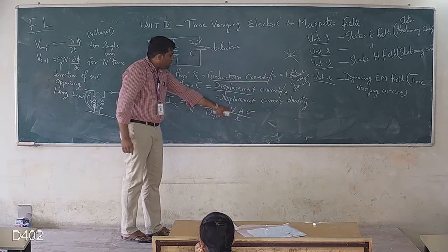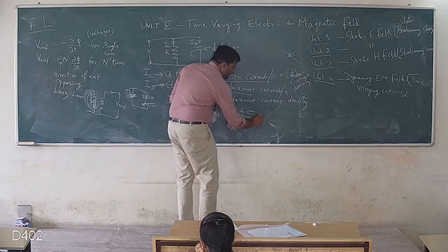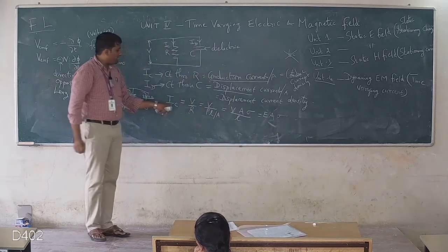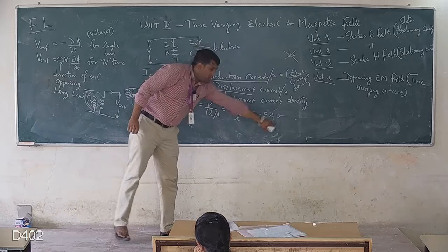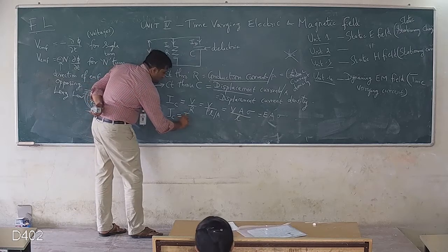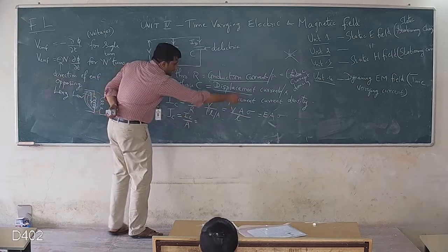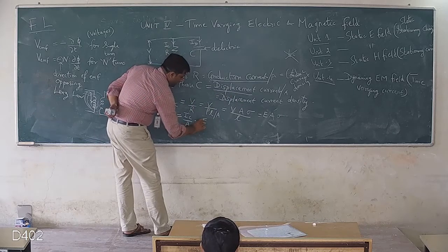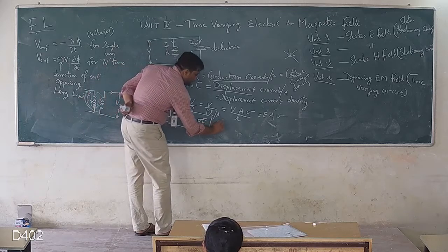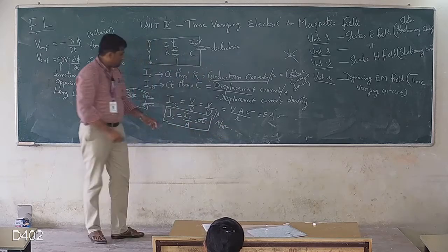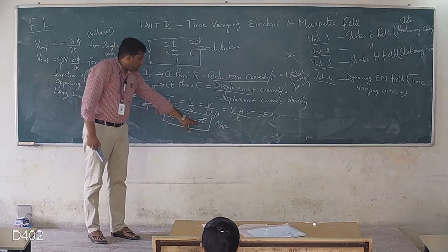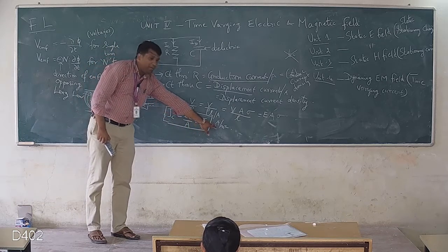So we can understand voltage per length is nothing but electric field intensity. So E A sigma. This is your conduction current. So the conduction current is equal to E A sigma. If I want to find the conduction current density JC, that is given by IC by A. If I take A outside, it will become sigma into E, which is nothing but conduction current density, and the unit is ampere per meter square. So in normal sense, we define conduction current density as conduction current per unit area, also sigma into E, which is ampere per meter square.